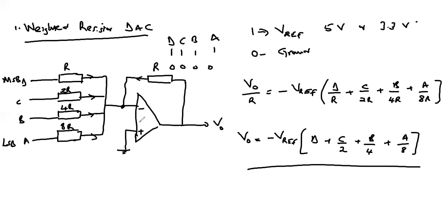We notice that whenever we want to increase the number of bits for our DAC, and every time we have to maintain a ratio of 1:2 from one resistor to another, or from one bit to another, then the value of the resistors will be increasing, and at such a point, the ratio between the lowest resistor and the highest resistor becomes very high.